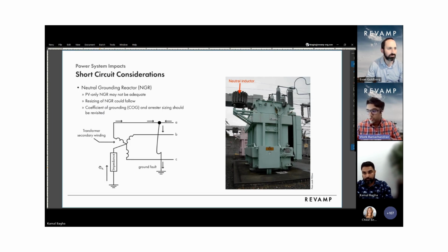All right, yeah. So before we get into short circuit, a quick note here. What we see increasingly with a lot of these PV BESS coupled systems is that the BESS yard is located really close to the substation. Yes, it helps with reducing the AC connection losses, but it also subjects the BESS system to higher phase and ground fault currents.